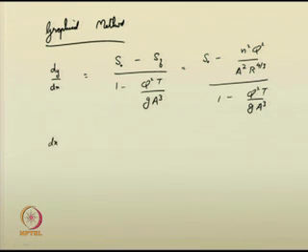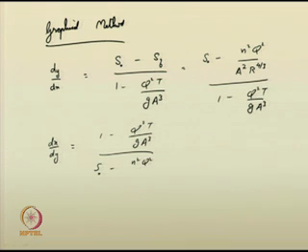So, what do you infer from this? You can write the inverse of this differential equation: dx by dy is equal to (1 minus Q squared T by g A cubed) by (S0 minus n squared Q squared by A squared R to the power of 4 by 3). You can integrate them.